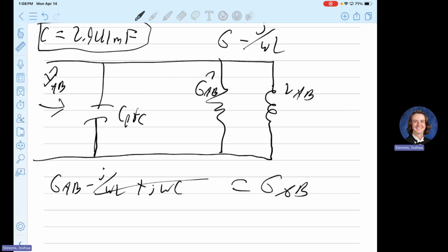Well, at that point we're just taking the impedance or admittance of it, so it doesn't matter. You're adding it like it's either impedances or admittances. But what you're saying is, in the current state where they're in parallel, GAB and LAB are summing together when they're in admittances. That's probably one thing I left out. I'm sorry. Yes.